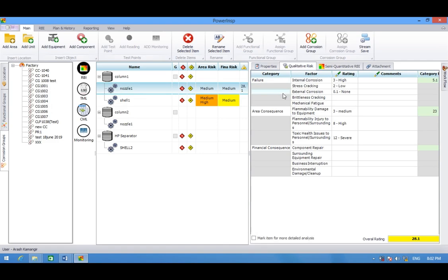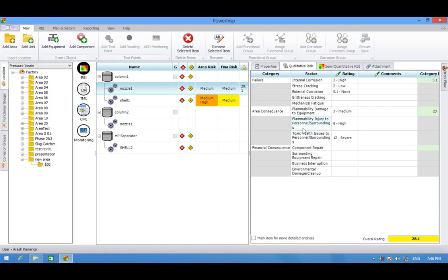Qualitative risk assessment is a very important yet effective measure to do a screening on a bunch of equipment to determine which equipment are going to be assessed using the semi-quantitative method. Using this approach, the user can significantly optimize their time and efforts and concentrate most of the risk assessment activities on those equipment with higher estimated risk values.